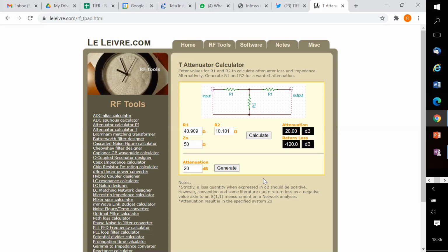No, but at port 2 the signal is going. By the way, you should be careful. I guess you come from the DC side, but you are also doing RF measurements. That sentence is just wrong. The power is not going to ground. You're thinking in terms of current and not power. Power is only being dissipated in the resistors. It's not going to ground anywhere. But I think you are getting close. You're just not phrasing it correctly.